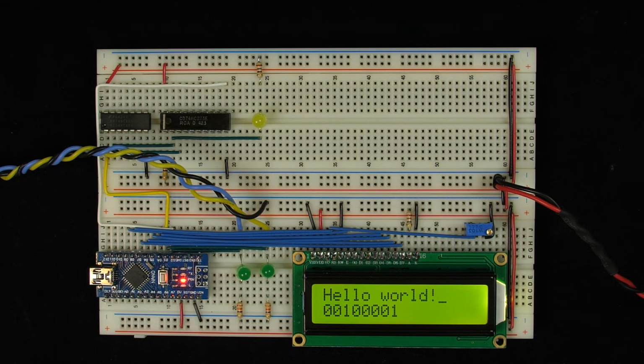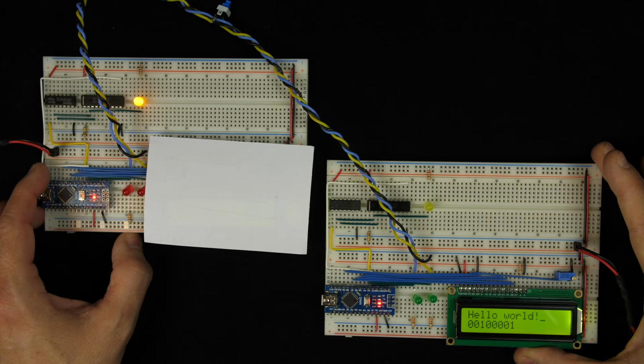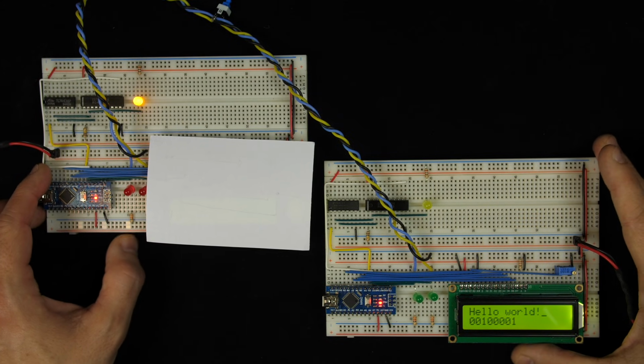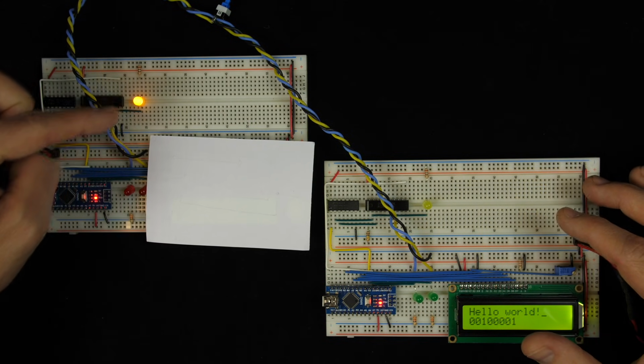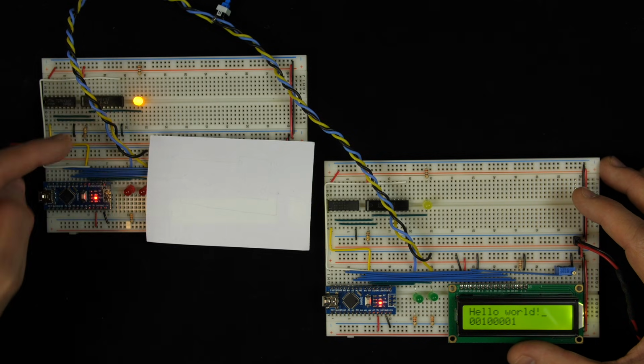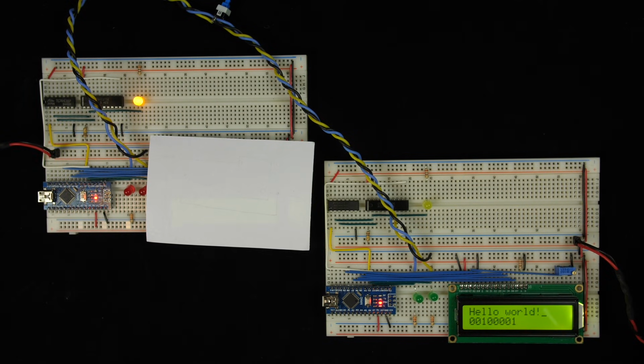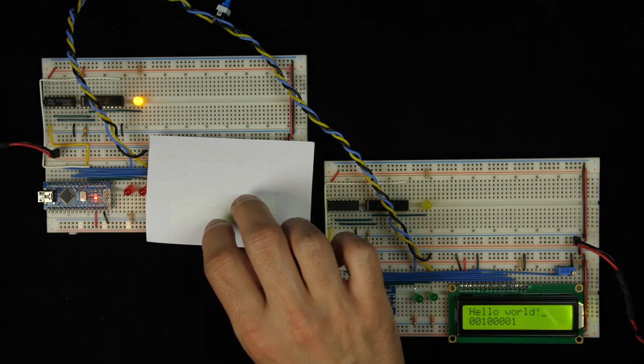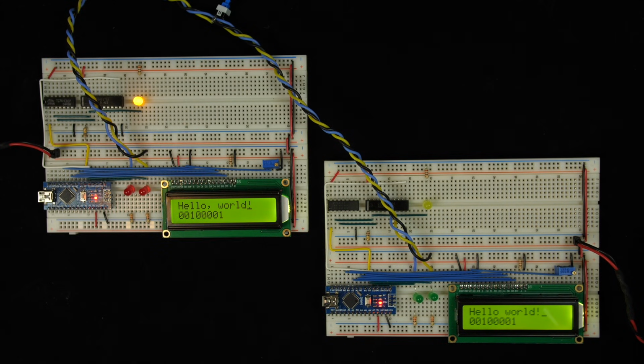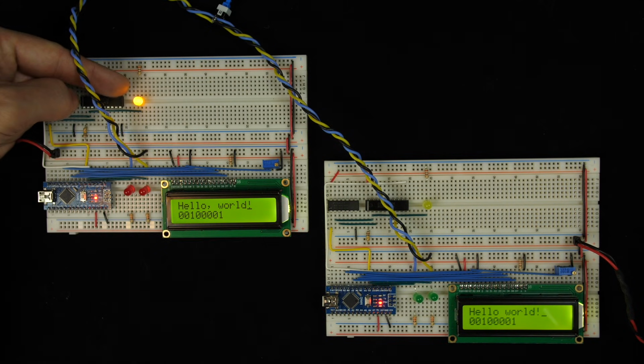So does that mean we received this message correctly? Well, from the receiver's perspective, there's still no way to tell. But if I show you the parity bit computed by the transmitter, I bet you can tell now. Since the parity of the transmitted message doesn't match the parity of the received message, we can't possibly have received the correct message. But of course, you couldn't know that without knowing what parity the transmitter computed.